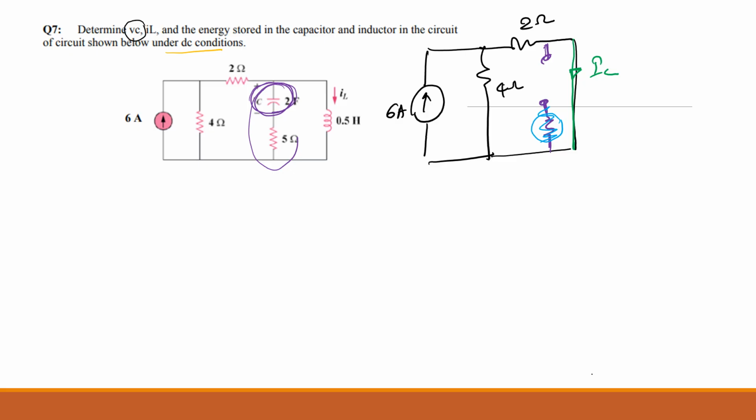Okay, now it's like your first week topic. So you need to find the voltage, current, this IC current and the voltage here. So I'll give you a few minutes again. Did you find it already or not? The current? No? Okay, can you find it? You just need the current division rule to find IC. Just one step. Current division rule to find the IC and think what will be your VC. You need to think it.